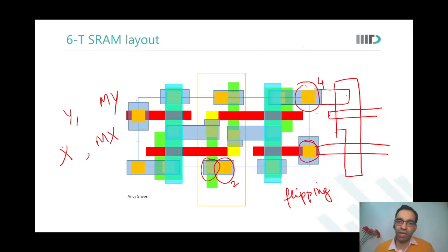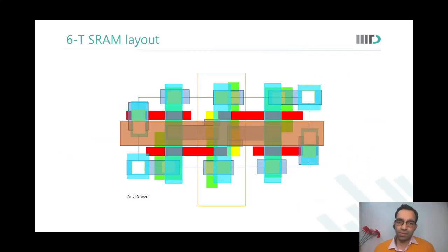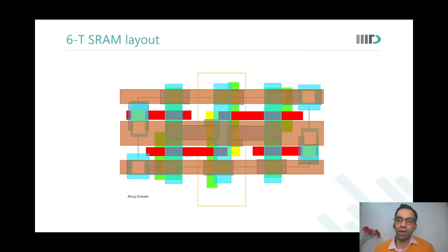We will just look at one of the array formations. So these are the bit lines, the word line stubs, the word line, and the ground connections. Now, do you see that in this particular layout, the word line that is running in the center has a lot of intra metal capacitance from the adjacent ground.